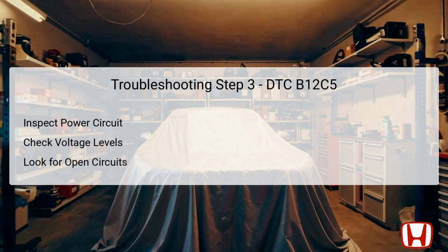If the connection shows less than 1 ohm resistance, this indicates that the circuit is intact. If resistance is higher or absent, it indicates a possible break in the circuit that needs repair.